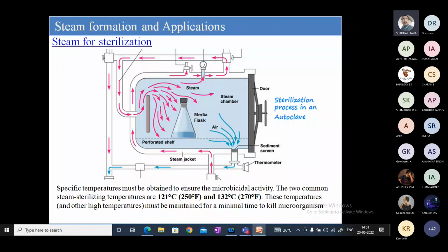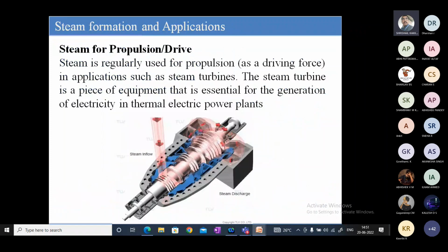One can see this. This is a turbine. The turbine will have blades and the steam. Here, as I told you just now, the steam available between the two horizontal points will have different quality. That is the dryness fraction and wetness fraction we are going to define. Once it reaches the saturated dry temperature, whatever heat is added, it will be at superheated temperature. The superheated steam will be used for the generation of power.